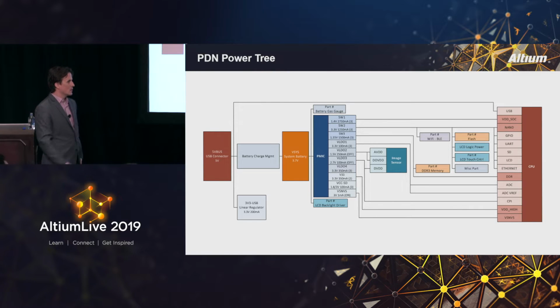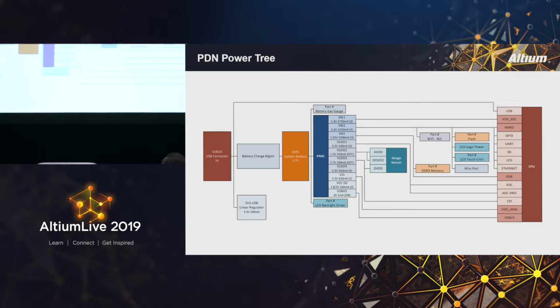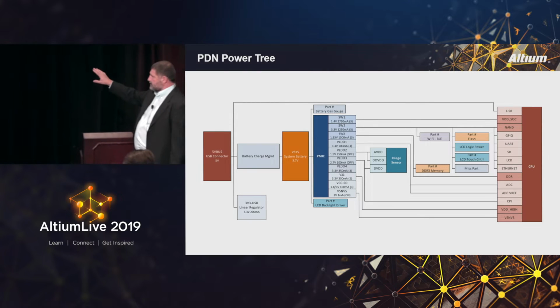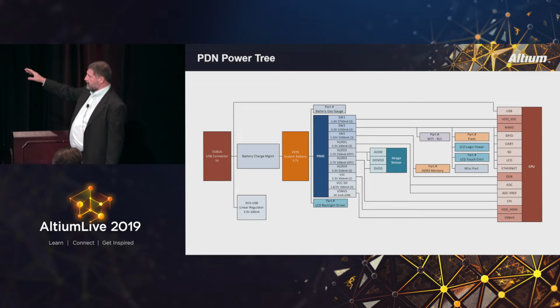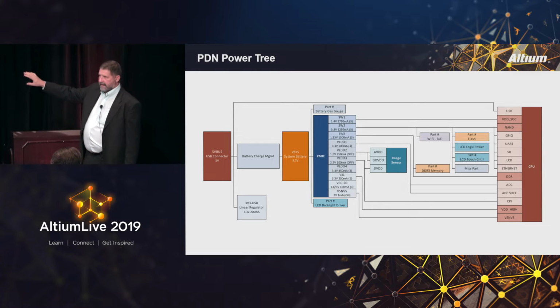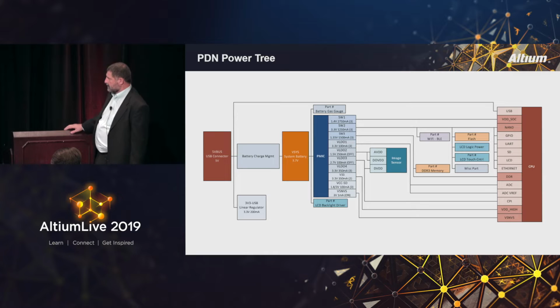Yeah, so as a designer, when I'm looking at this, I see that there's a charging system, and then that's followed by a PMIC, which is going to be very precisely laid out. If you look at most data sheets for those, they're extremely long, and there's almost always something on the PCB layout because it's super critical.